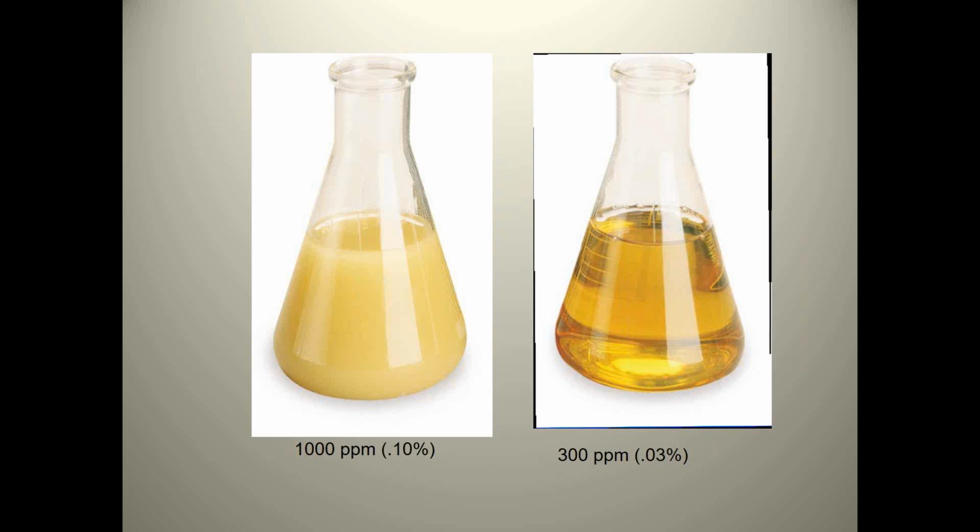Maybe if you would have taken a sample when it was perfectly dry and a sample now at 300, you might be able to see it. But like I say, in most cases around a facility, if you put it in your sample jar, you're not really going to see it at those low levels. Now, the one on the left has 1,000 parts per million of water. So now it's very visible. A lot of times we'll see this in hydraulic units or gearboxes where it gets foamy.